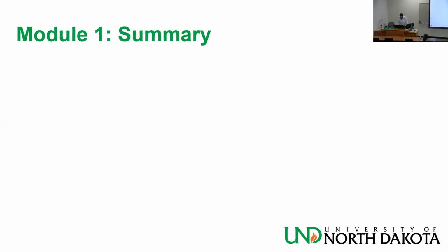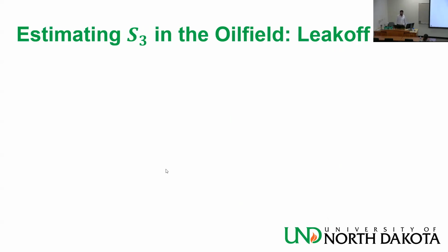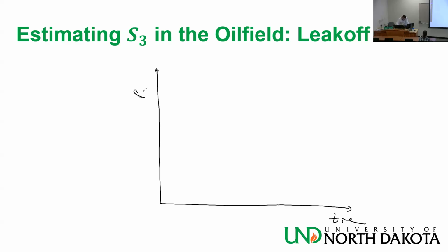Oh, and then we talked about leak-off testing, and I remember I drew a leak-off test, and we talked about when does the fracture start, the fracture initiation, when it opens, when it closes. We had a lot of discussion about time and pressure.